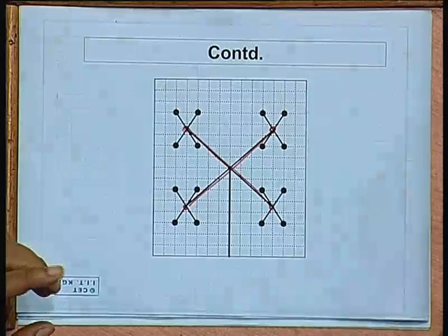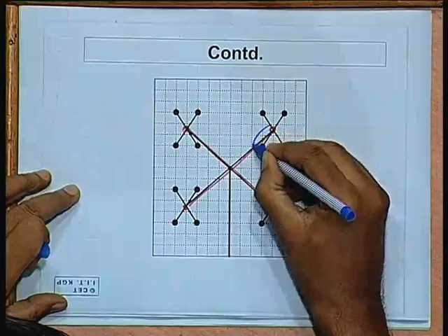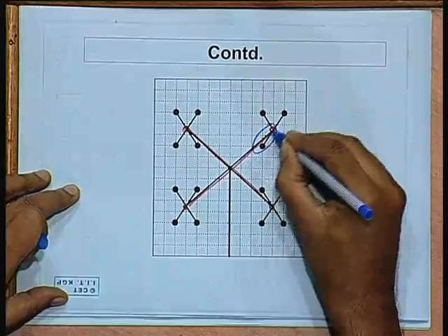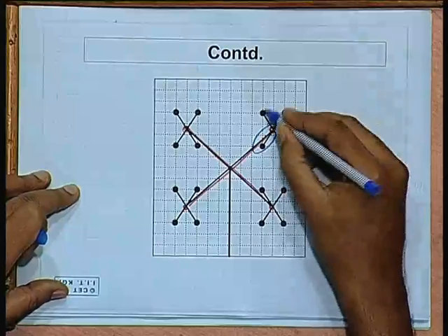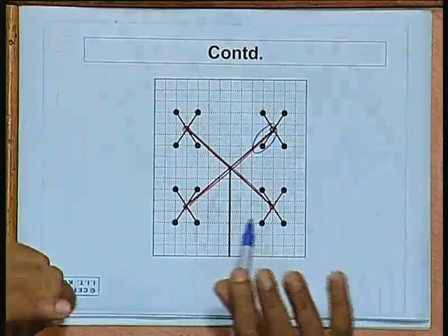Now, as I said, as you do this, there are some pairs of wires, like here these two lines are so close together, but the other lines are not close together. So, there will be unequal coupling between these pairs of lines. So, the delays of the different segments may still be slightly different.